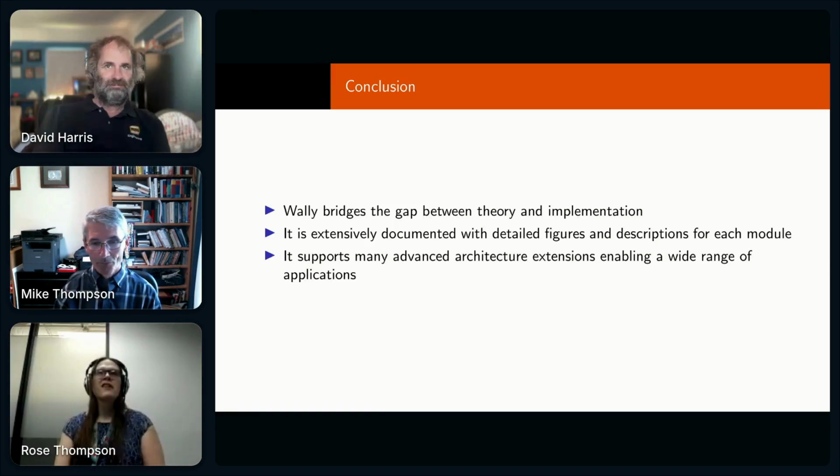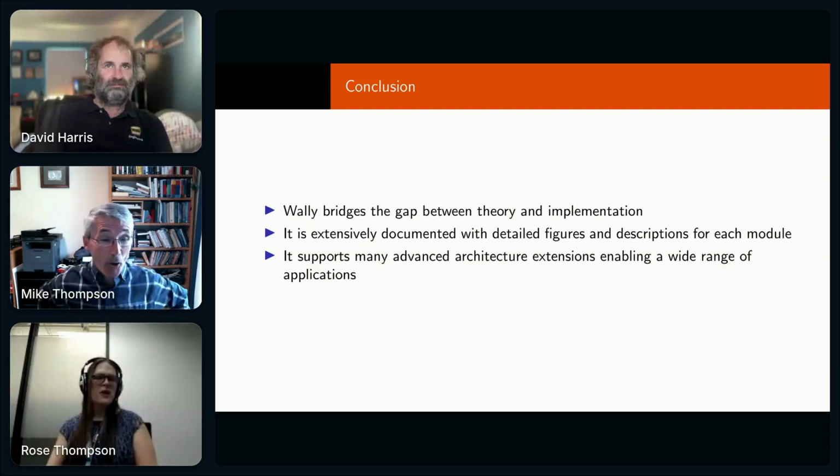The specific bug that really tripped me up was that the little chip that did the UART to USB conversion was configured in loopback. So when the Linux kernel would do a kprint out, it would loop back the data. Anytime it would print out data, it would just loop back, and it was configured in a mode that was the same baud rate as the expected terminal. So it would just print out random garbage to the screen. It was really confusing. We've all been there. And a good debug tool is great.